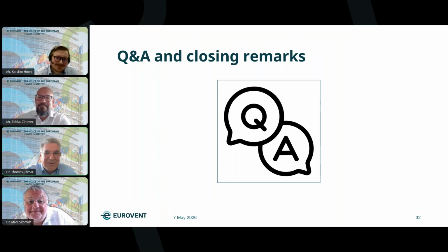Yeah, here the Eurovent guideline and the standard very much focuses on HVAC and indoor air quality. So recommendations for gas turbines are very different to what we are seeing here, because in a gas turbine, typically it's about corrosion of blades, for example, stuff like that. So it's different gases to look at. When we talk about hot gas corrosion, it might be chlorine. Then we are typically more on the particle filtration, because that is typically coming from salt and sea salt.